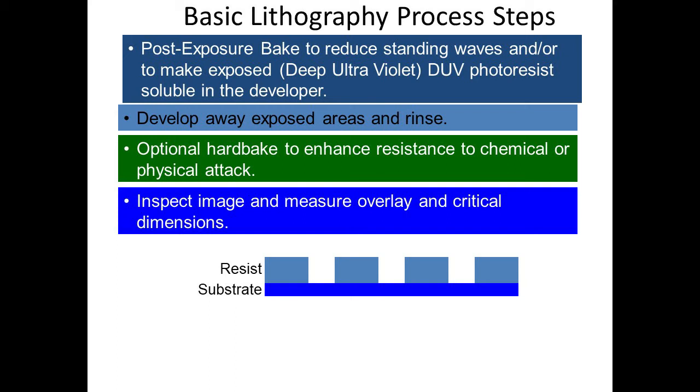During this etching process, you need your hard baked photoresist to be tougher, so that it can withstand the other processes. After you have done your hard bake, you will inspect and check your image and see whether all the pattern is in place.